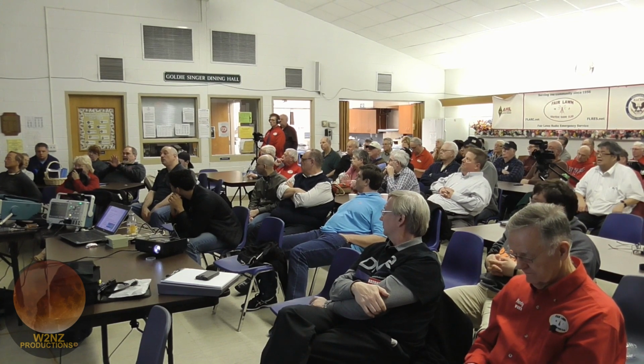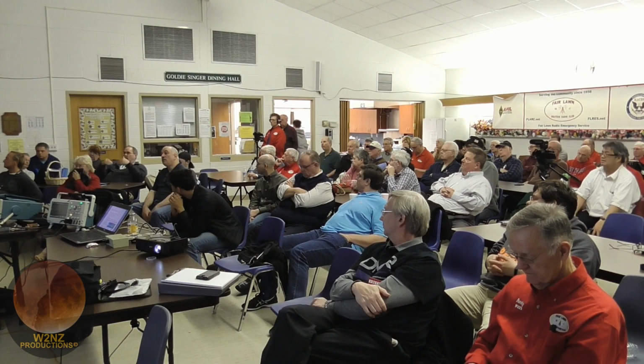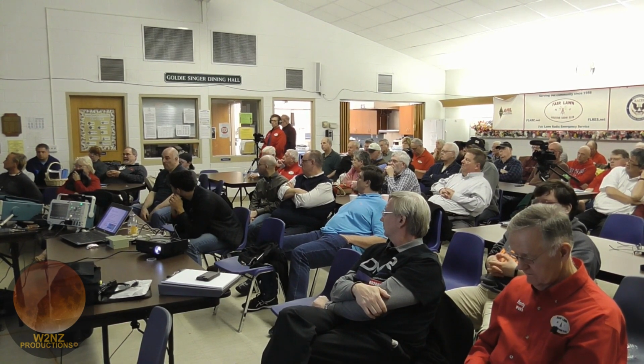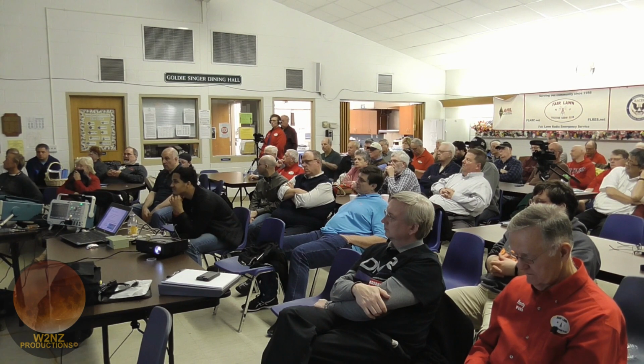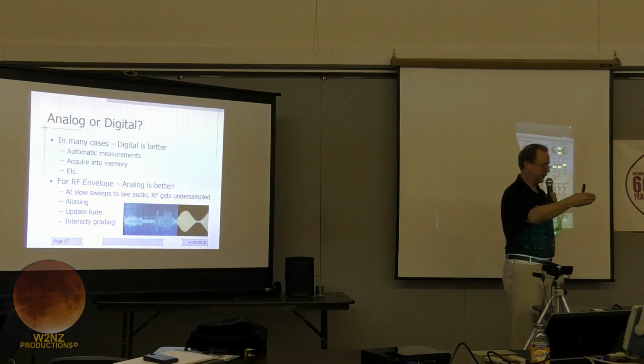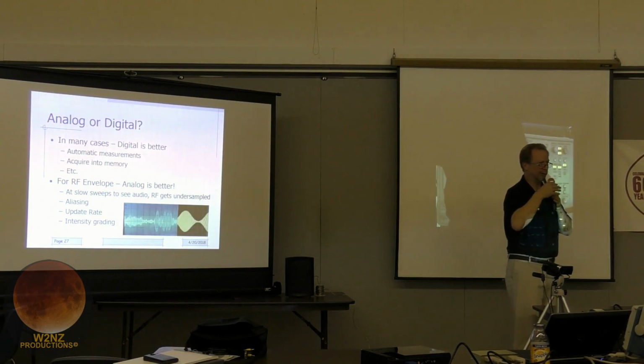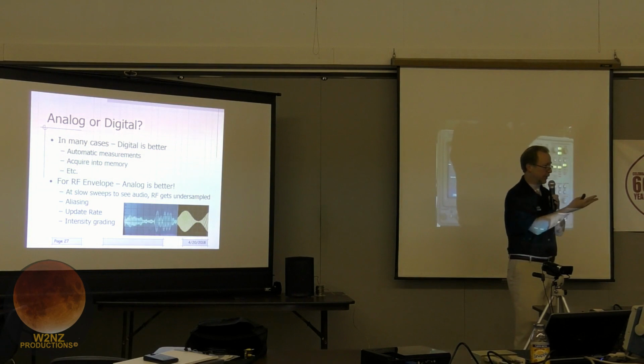So Alan, I've seen in spectrum analyzers where they actually will give you the intensity in color on the waterfall. Yep. So I'm assuming we could do the same thing in a digital mode, not sacrifice sampling, and maybe with color. Yeah, some digital scopes do have a color intensity grading, as opposed to a color bitmapping type of thing like you have on real-time spectrum analyzers.